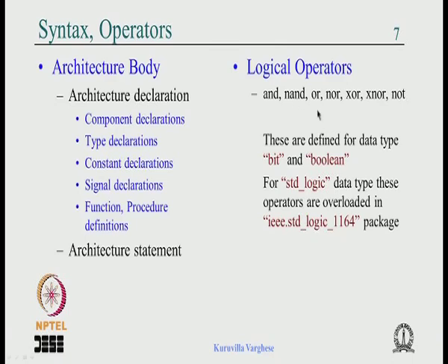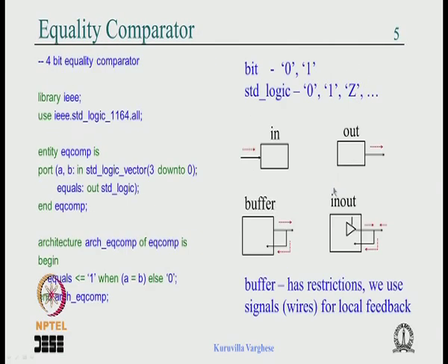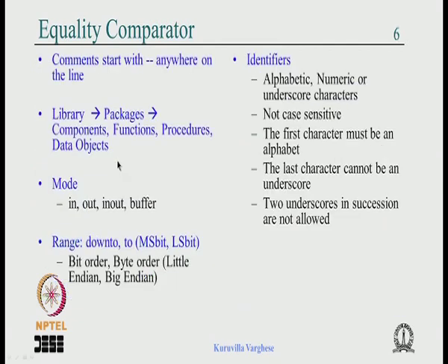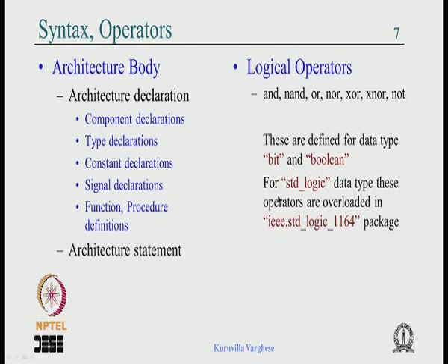Overloaded means whatever was written for bit is rewritten for the standard logic data type. So the moment you declare use IEEE.std_logic_1164.all, we can use AND, NAND and all that here in the statement region. The all means everything in it, that is, the entity and architecture following this use construct can use whatever there is within this particular package. So that is the logical operators.